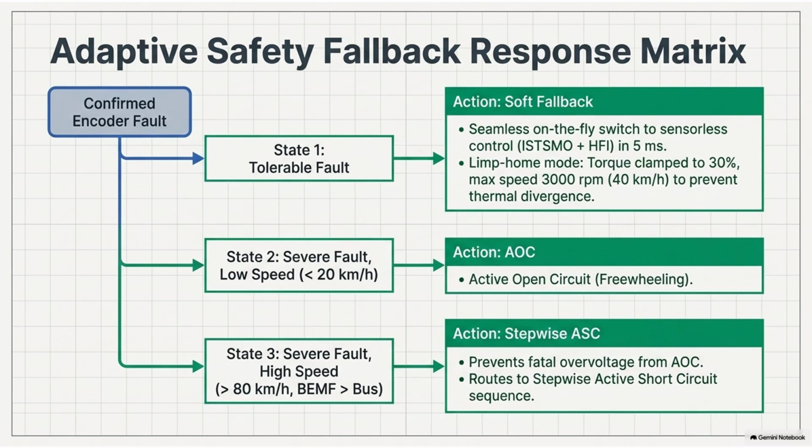Well, they utilize strict, unyielding design mandates that lock the bill of materials. Like, the specification explicitly dictates the architecture of the analog front-end filter circuits. These are the circuits designed to clean up the analog signals before they hit the analog to digital converters. And the mandate requires the exclusive use of Class 1 C0G, also known as NP0, multi-layer ceramic capacitors. And the choice of that specific dielectric material is entirely about thermal stability. We talked about the thermal shock earlier, going from -40 to positive 150 degrees Celsius.